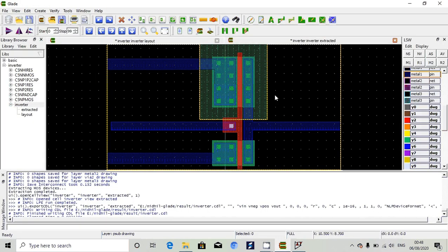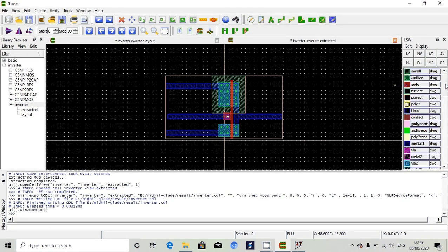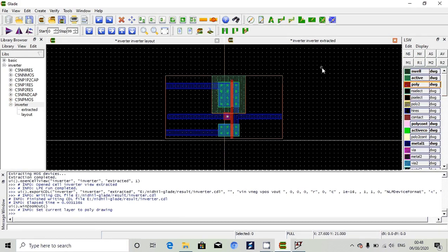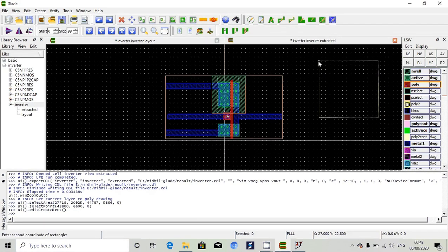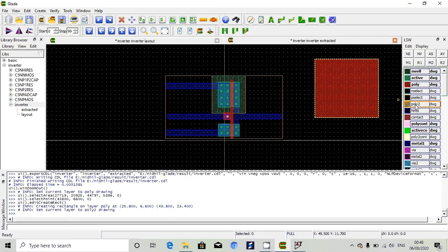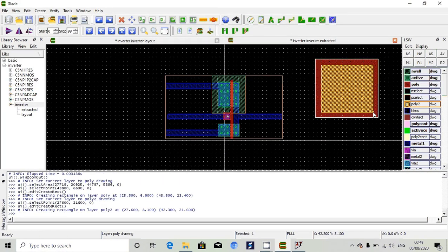And one more thing I would like to say is, if you want to draw a capacitor or a resistor, what you can do is, if you want to draw poly to poly cap, you take one poly here like this and draw it. Take R and draw it. Then we take poly 2, again draw it, poly 2. In between that you have dielectric. Now this tool cannot understand that you mean it for a capacitor.